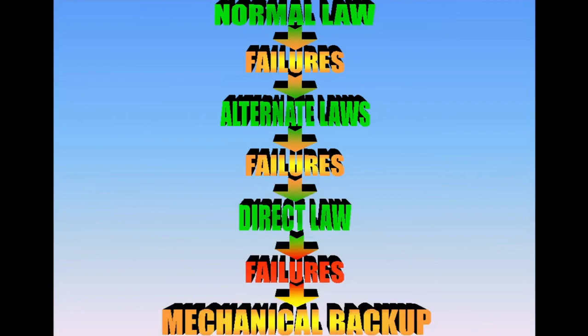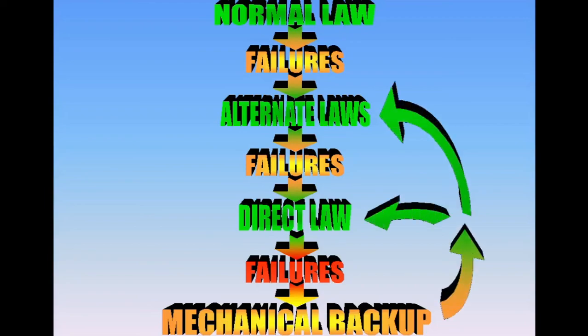In most cases, resetting the flight control computers will allow recovery from mechanical backup to either alternate or direct law, depending on the type of failure.